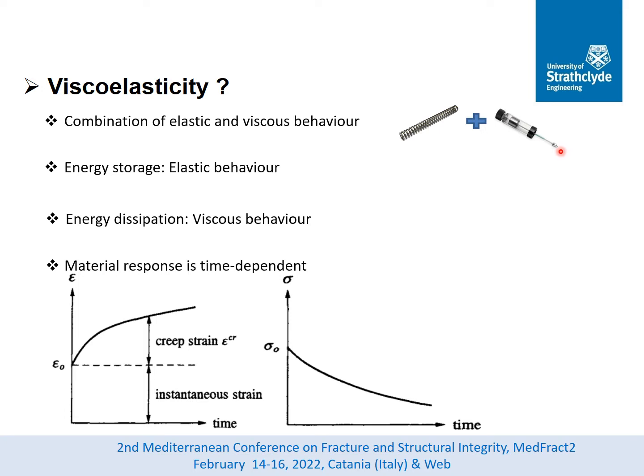The material response of viscoelastic material is time dependent. As you can see on the left side, the material continues to deform under a constant loading. This phenomenon is also called creep. At the same time, if a material is under a constant deformation, the material begins to relax and the reaction force or the stresses decline gradually with respect to time.